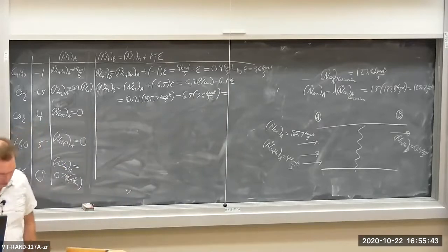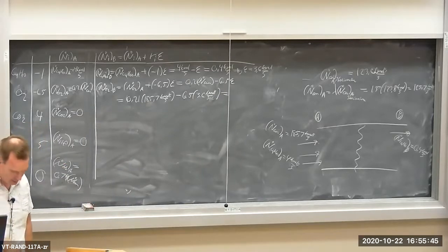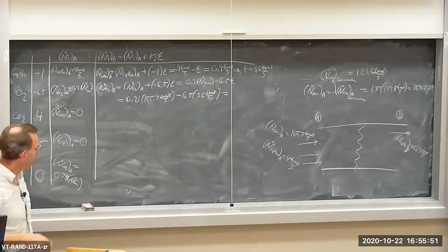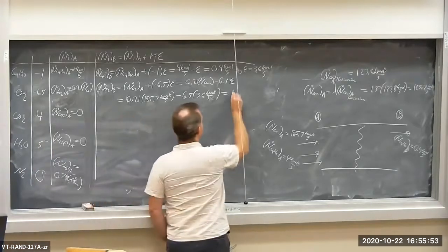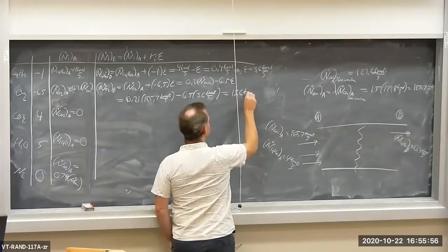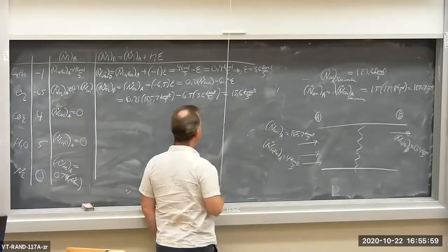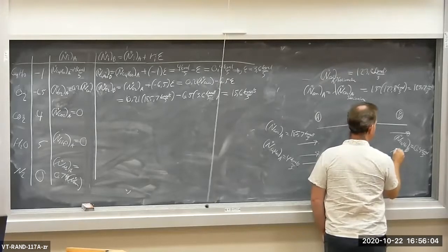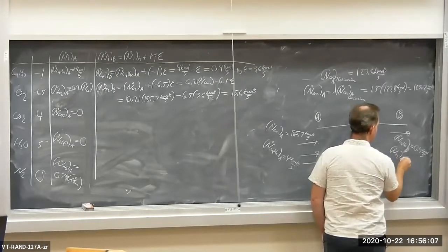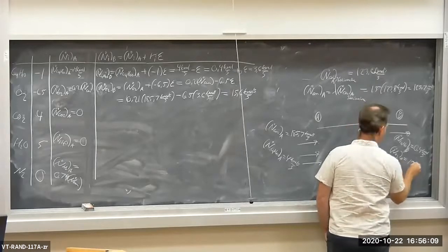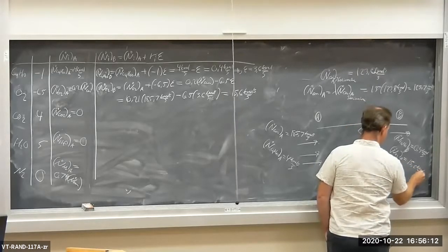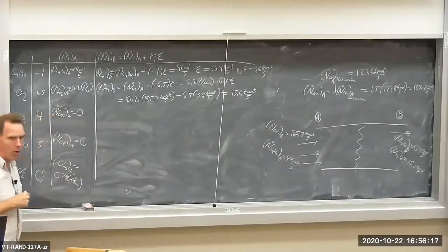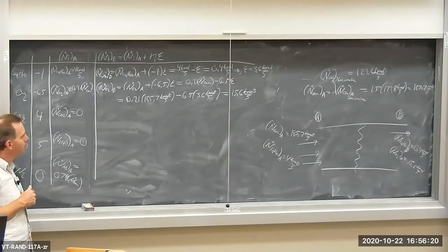And you get an oxygen outflow rate of 15.6 kilomoles per second. So that's the outflow rate for the oxygen, O2, in the products. Remember in the previous example, there was no oxygen in the products. It was stoichiometric combustion.